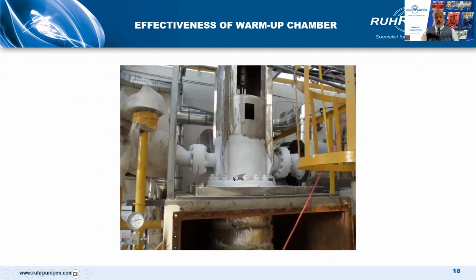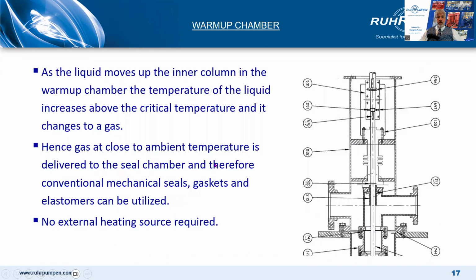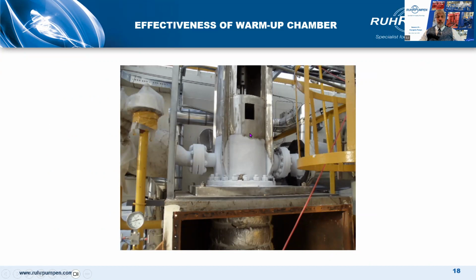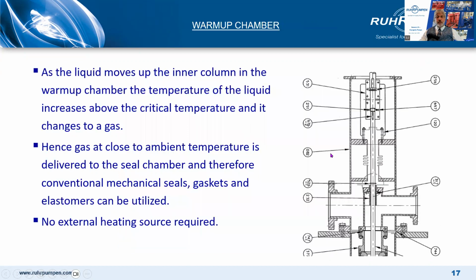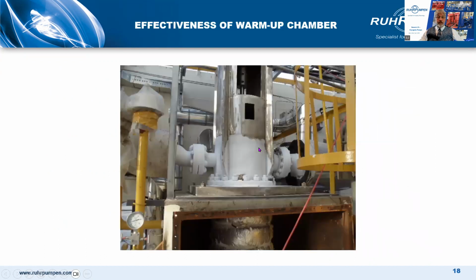As you can see in this photograph, and a few more photographs which I'll show you later on, we can see how effective the warm-up chamber is. We see ice forming in this area around the suction and discharge nozzles, which is here. But here in the warm-up chamber, around the warm-up chamber, so around here, it's already no ice. We've got ambient temperature just a few inches above the nozzle head.